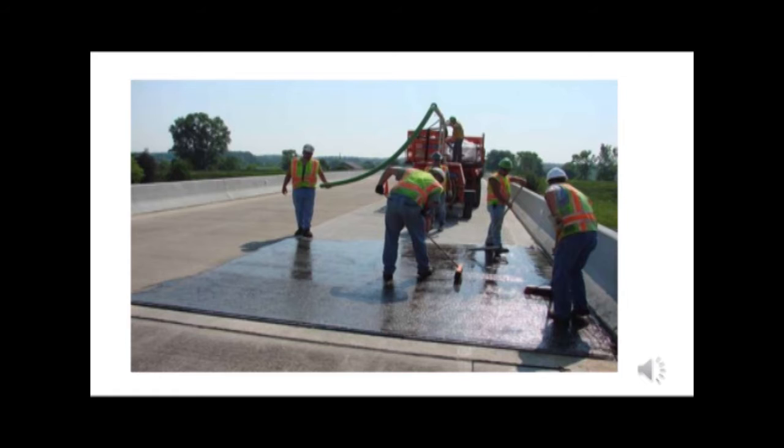So what we have is, with the sub base and base course, we have DLC and PQC. We have dry lean concrete, and we have pavement quality concrete. Pavement quality concrete for this one is M40. Beneath the DLC we have to clean it, and we have to provide the pavement quality concrete, and that is to be provided with the contraction joints and all. So this is the paving of the road of the bridge slab.